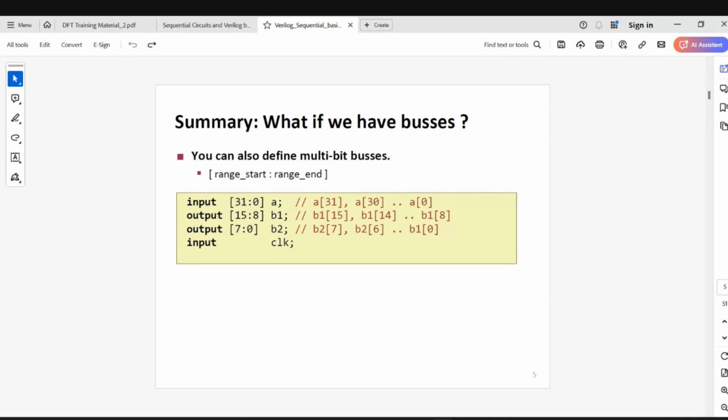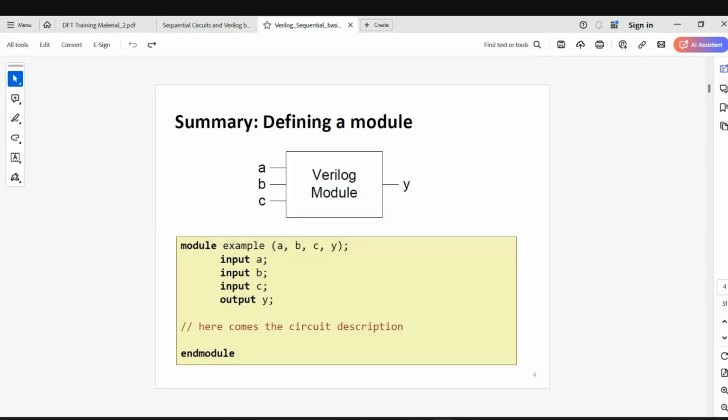Yes. So this is a simple Verilog code. As you can see here, we have taken an example. We did not also take any gate here. Going forward, we'll see a little bit of examples of some combinational and sequential circuits, how we write the code. So the module example can be any functionality of a logical gate or combinational circuit or a sequential circuit, followed by brackets, normal brackets, with the number of input and output ports you want to have for your desired module.